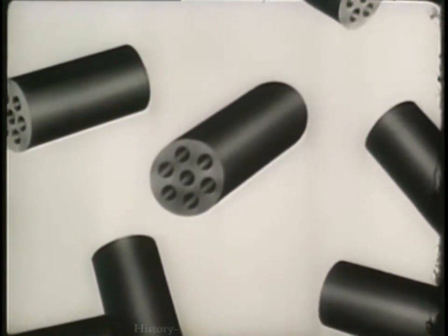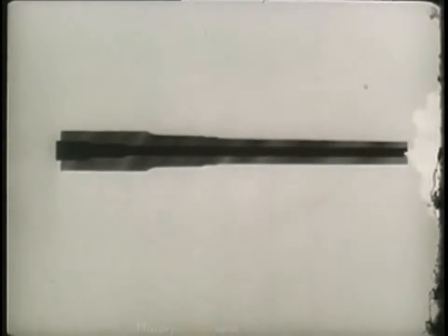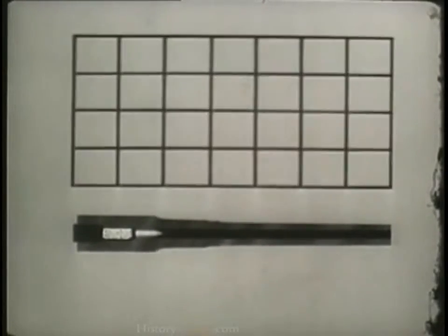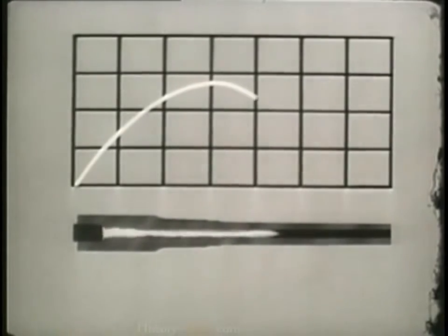When we burn a suitable charge of progressive grains, the pressure is moderate and sustained, sending the projectile out of the bore with a continuous push. This kind of pressure action is just what we need to get high velocity in long-barreled artillery.